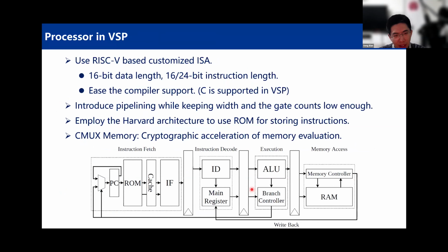So here's a very rough overview of the processor. I'm not sure how many in the audience are really familiar with computer organization, because this is basically a hardware class, so we're just going to briefly summarize. We have designed a 5-stage pipeline. We have different pipeline stages where the intermediate data is stored in a register to pause and to allow different stages to work independently. Basically, that's how pipelines work.